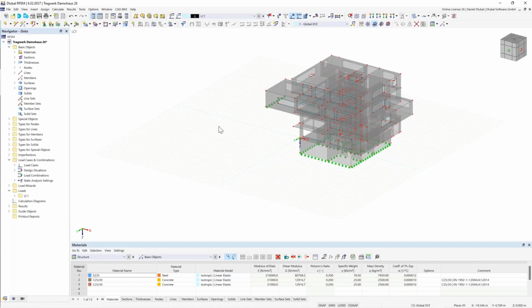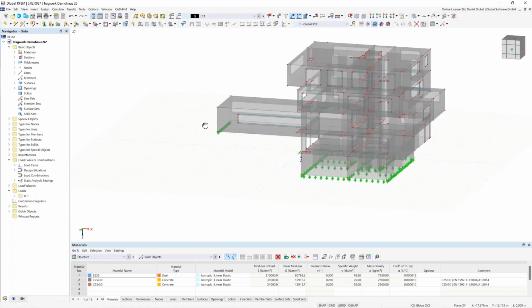and every time when I work with different interfaces like importing DXF files, SAF files, IFC files, or also using some direct interfaces, I, as a structural engineer, need to do some checks. So the first check, in my opinion, is always the completeness of this model. So I will do here some basic checks if the connections of the systems are correct. So in my opinion, at first view, it seems everything okay. So this looks pretty nice.